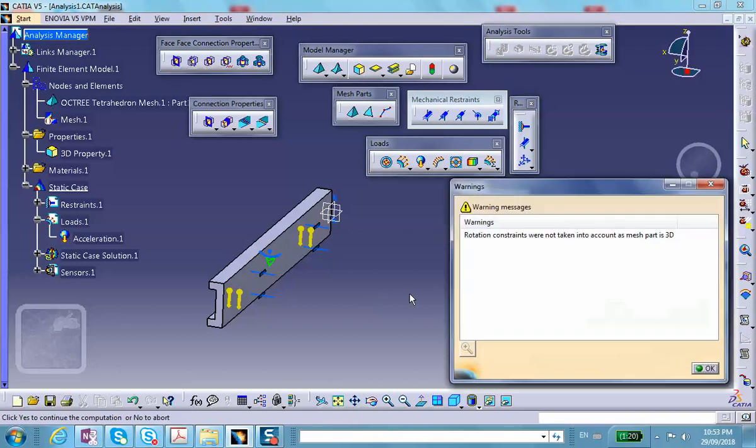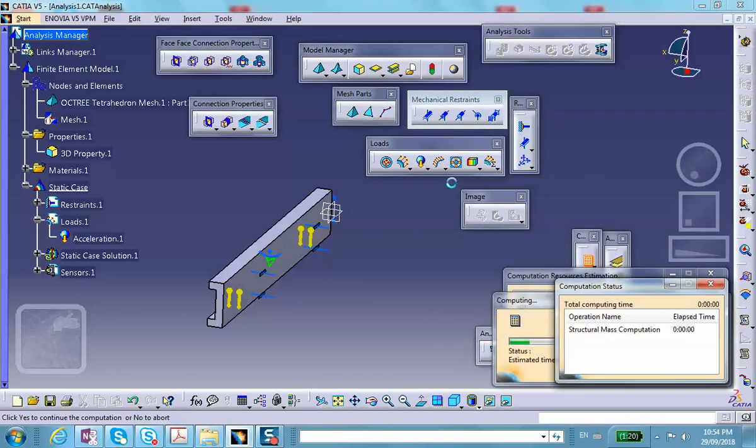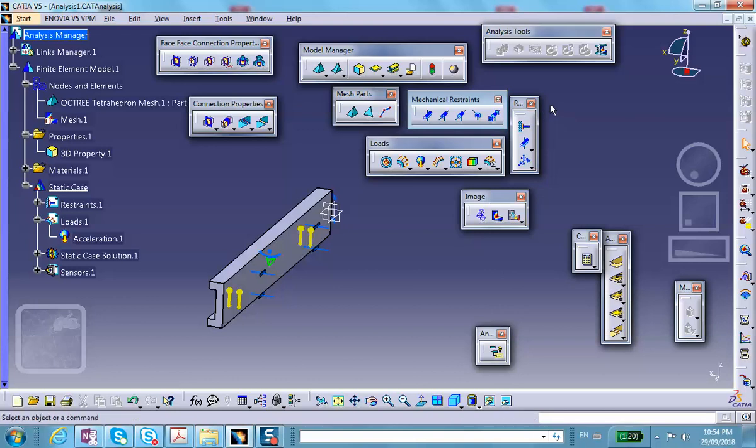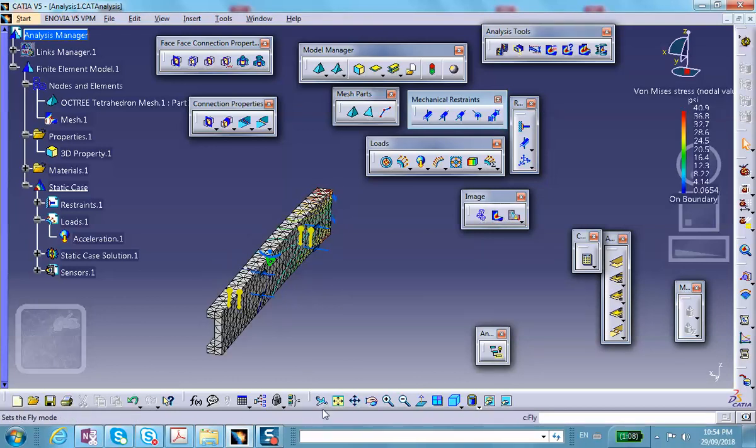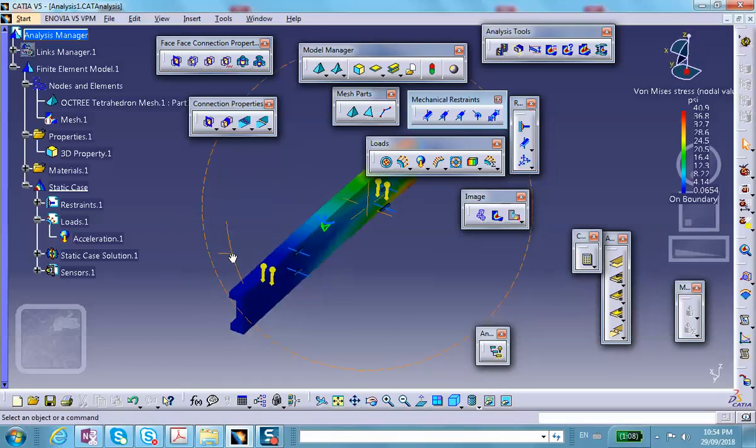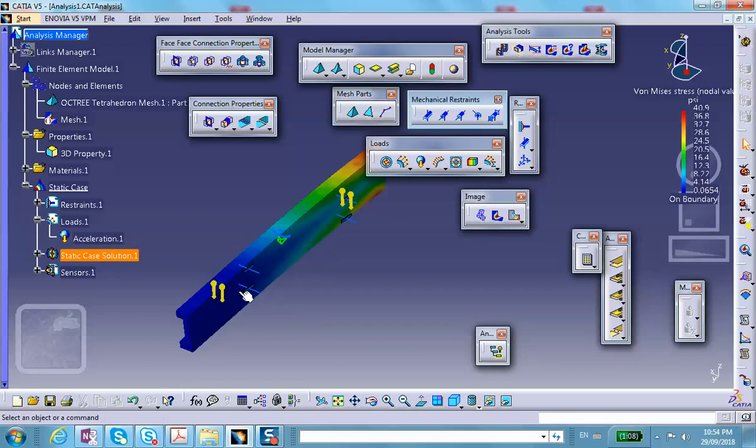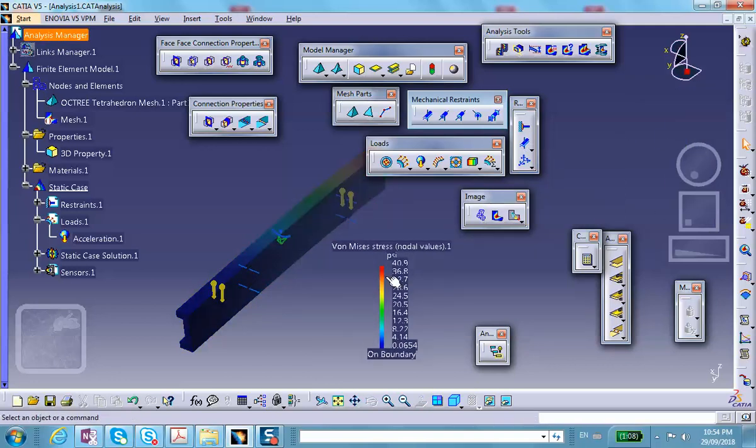Run it again. Forget about the warning. And now if you look at the deformation, where is that? Von Mises stress right there, and change the material shading. Yeah, same kind of thing. We did not have to model the entire object. We needed to model only half of it because there's nothing we gain if we create the second piece. Now these numbers are very tiny because this is a fat, thick piece of steel which is hanging under its own weight. There's going to be extremely small deflection, and therefore extremely small stress. Okay, hope this